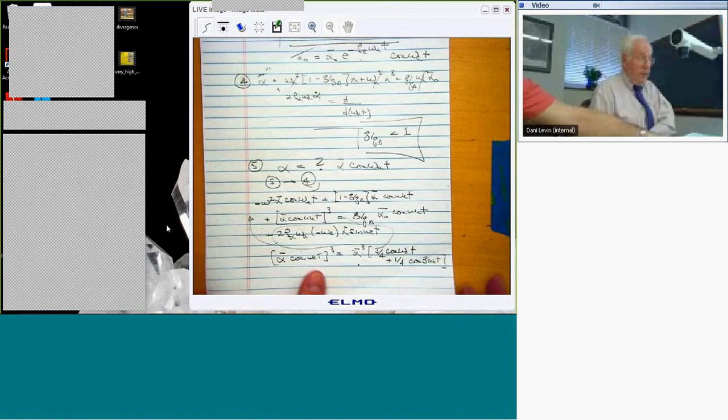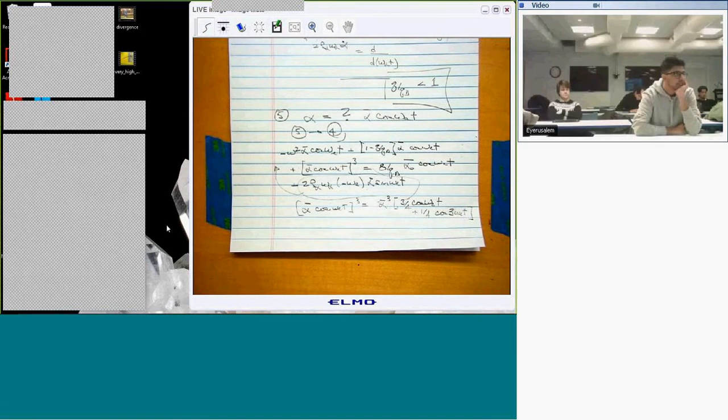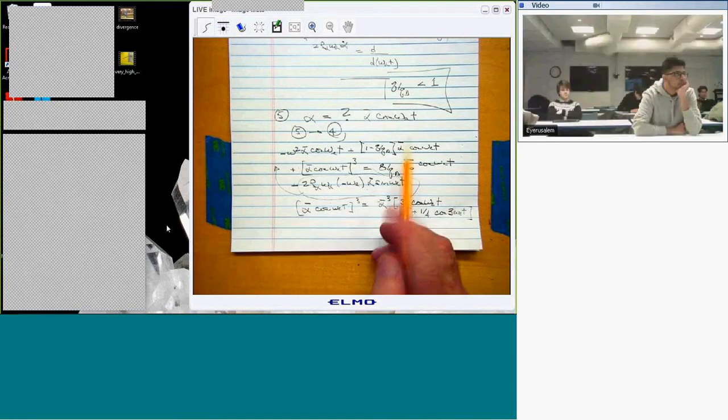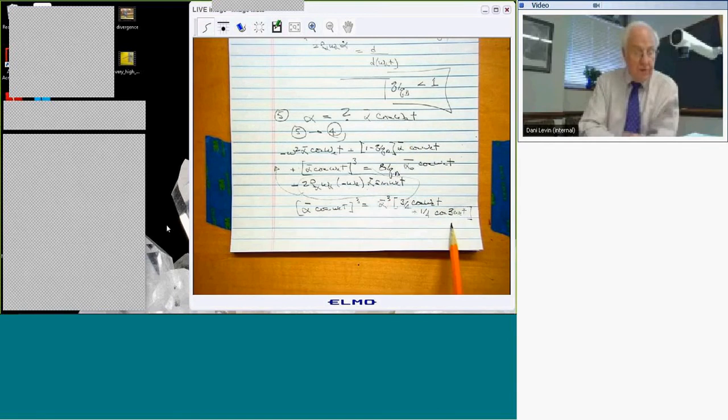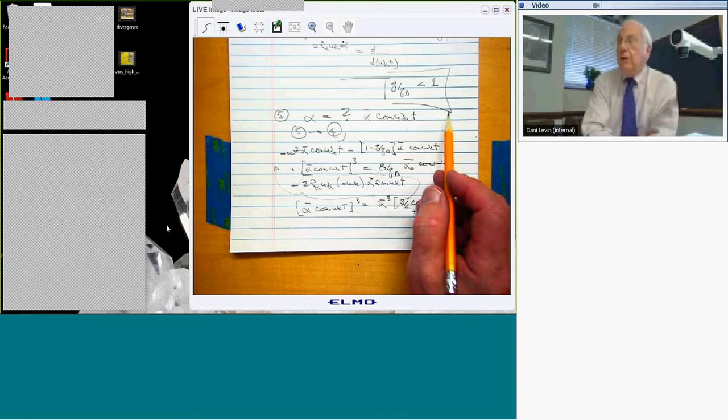Okay. Now, the way the game is played is I need to balance the harmonics. That is, I need to balance all the coefficients of cosine omega_E t and sine omega_E t and cosine 3 omega_E t. Right? Well, I can't really do anything about cosine 3 omega_E t. Why not? Well, because I started out with a solution that had this form. If I really thought that was important, I should have alpha bar cosine omega_E t plus another coefficient times cosine 3 omega_E t.